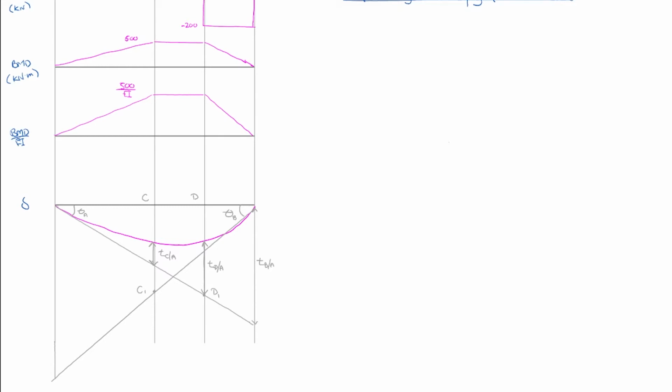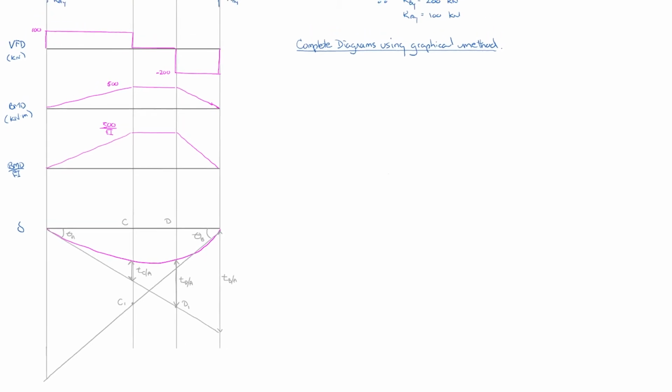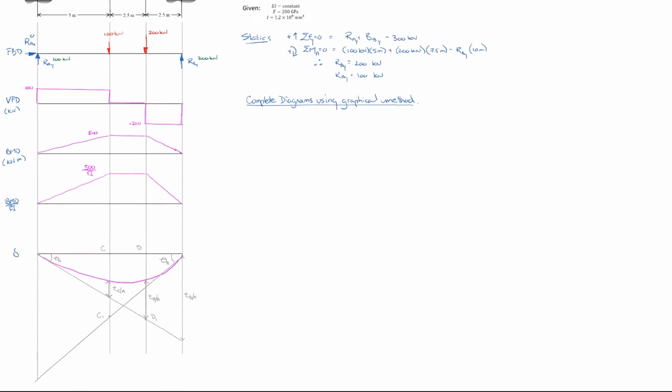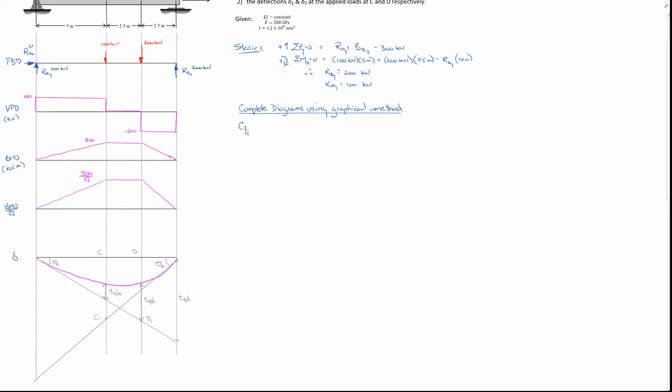All we now need to do is to go through the mechanics of the theorem to apply it and calculate what the actual displacements are. So I guess let's do that. So I'm just going to come up here and calculate our theta at A, and we'll start there. To do that, I'm just going to make a quick representation of my bending moment diagram so that we can show our various distances and calculations and areas on it and follow the logic.